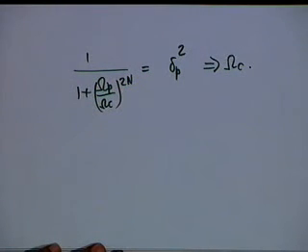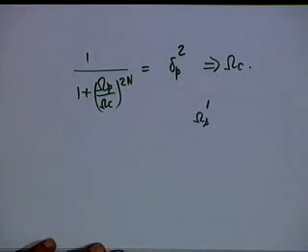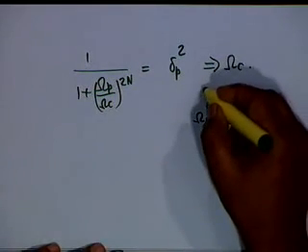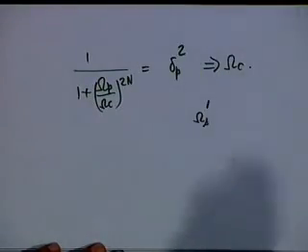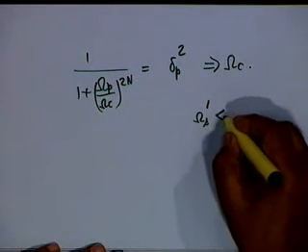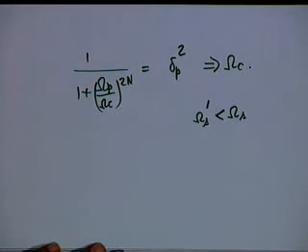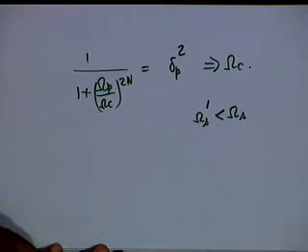Then omega s that is actually obtained, realized, if n is greater than that quantity, half of ratio of 2 logs, then omega s prime shall be less than omega s. In other words, you are bringing the stop band in the transition band, and that is a welcome feature. Where you required 40 decibels, if you get 60 attenuation, you are happy.